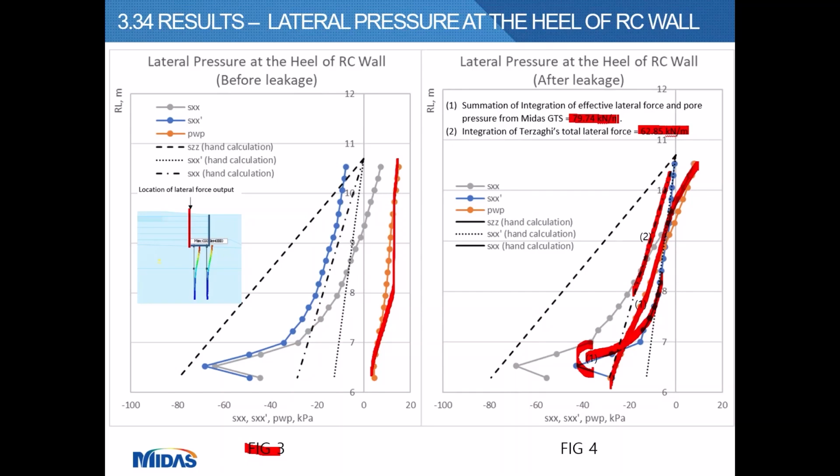In other words, if the engineer did not provide the subsoil drainage behind the RC wall and designed the pile using the total stress following the effective stress soil mechanics, and assumed there's no pore pressure, the pile may be under-designed.